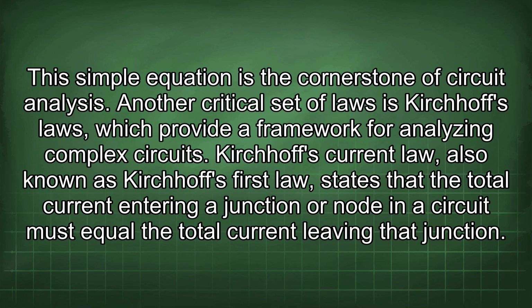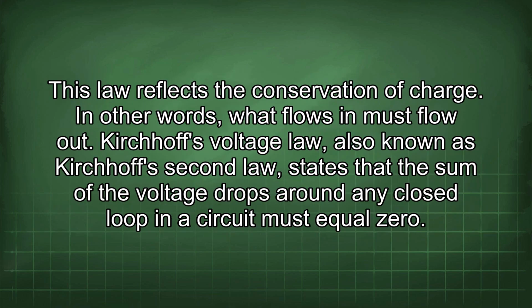Another critical set of laws is Kirchhoff's laws, which provide a framework for analyzing complex circuits. Kirchhoff's current law, also known as Kirchhoff's first law, states that the total current entering a junction or node in a circuit must equal the total current leaving that junction. This law reflects the conservation of charge. In other words, what flows in must flow out.